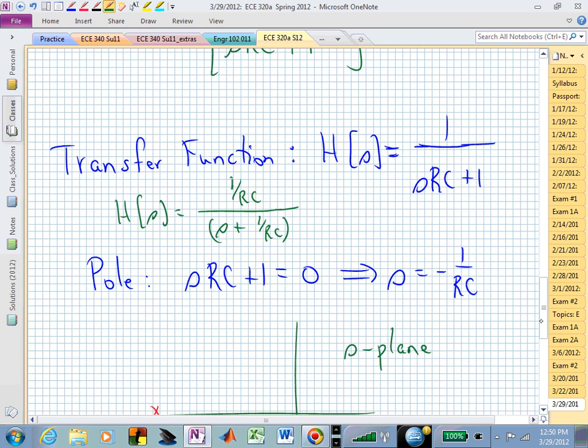But this is our transfer function, and now do you have a better feel for just an RC circuit? Now when you see that RC circuit, you might see a pole zero diagram, you might see a Bode plot, or you might see the RC circuit. I want you to be thinking all three. And the other thing that I want you to be thinking about is if we inverse Laplace transform that capital H of S, which you should be experts on by now, what would the little h of t be?